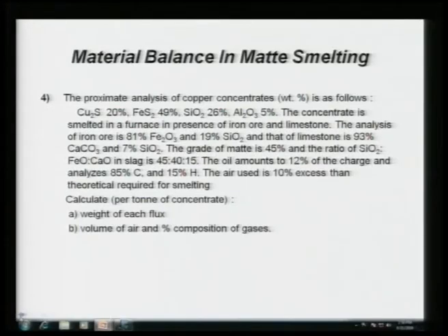and air is 10% excess. You must have noticed by now in various lectures, on roasting or smelting, that the chemical reactions accompanying the transformation of one phase to another do not occur with the stoichiometric amount of air. You always require some amount of excess air. Industrial operations always require an excess amount of air. It is up to the skill of the operator how well you control it. Somebody may do 10%, somebody 20%, somebody even 30%.